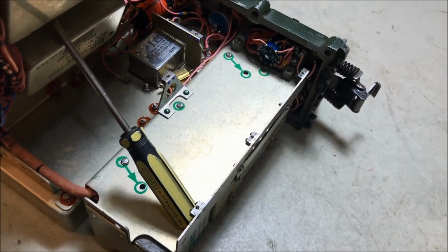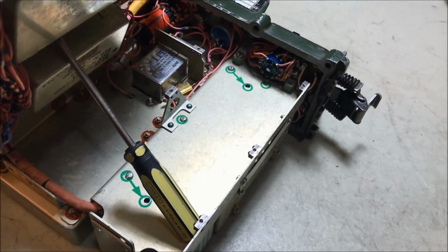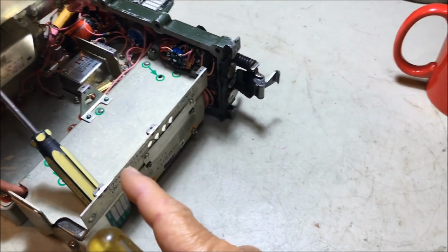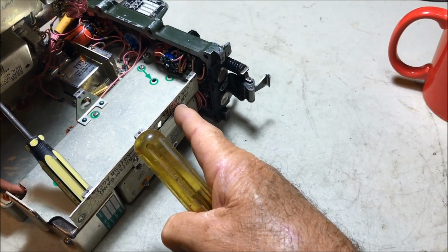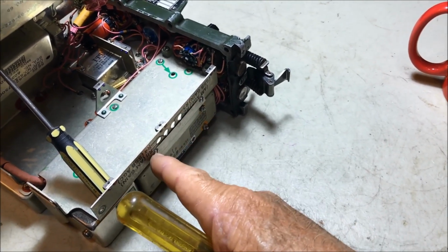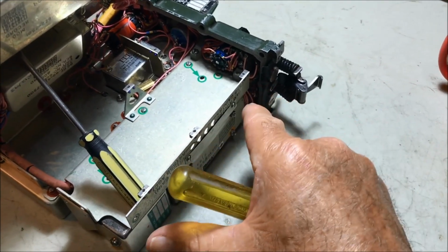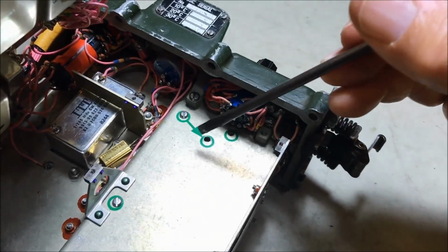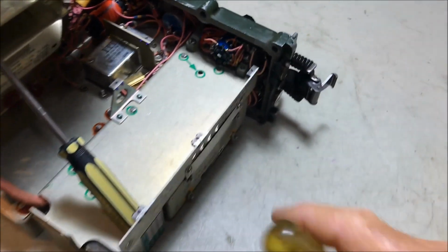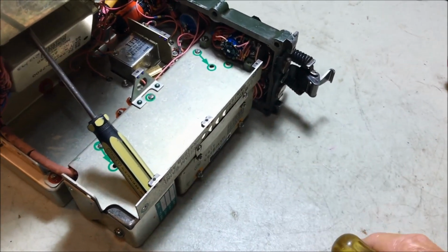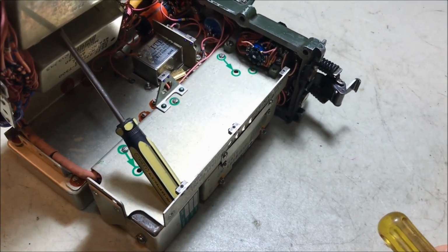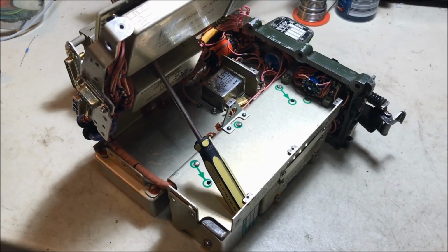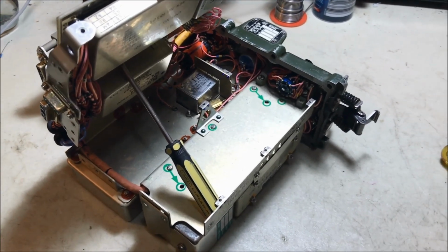But if ever you see in the text, move the synthesizer out to the service position, you see the arrows? You can undo the screws and pull, or you've got to take these 2 off here on the side too, by the way. They also hold the synthesizer in. So you can undo all those screws and pull the whole section out; it moves out exactly that far. You put the screws back in over here, and it re-secures the synthesizer in what they call the service position, which gives you access to the rear connections. But to tell you the truth, it's still pretty cramped in there, even in the service position. So let's get those out, and let's get some access into the back of the synthesizer.